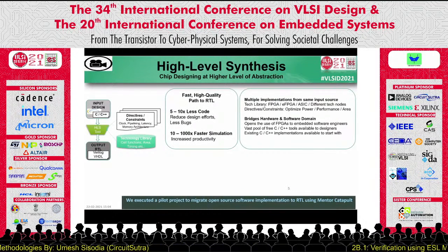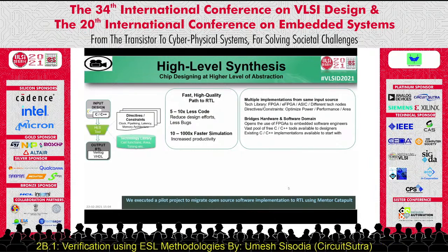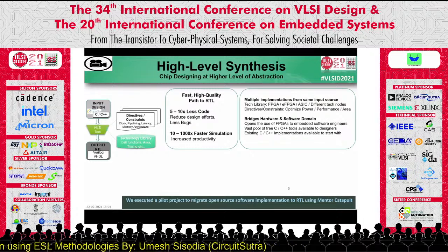Synthesis is an emerging use case of ESL, which is becoming quite popular in the industry now. It allows us to design chips using languages like C, C++, SystemC instead of designing using RTL, and an HLS tool can be used to generate the RTL from the high level design.